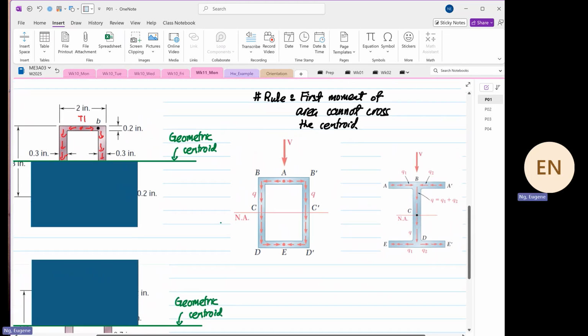For the one that I've just drawn the shear flow, or we look at the top, is this a box beam or white flange analysis? It's more like a box beam, yes or no? Why? What is common is you have one terminal over here, you have one terminal over here. The Q split into what? One Q goes one side, the other Q goes the other side. So the top is more of a box beam analysis.